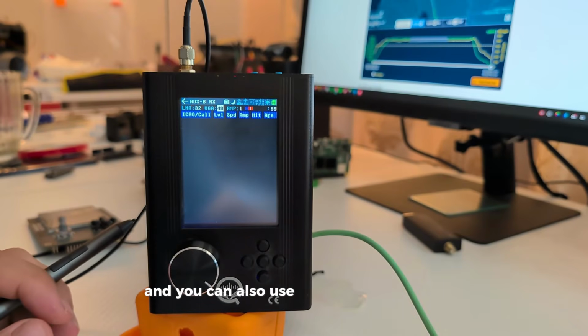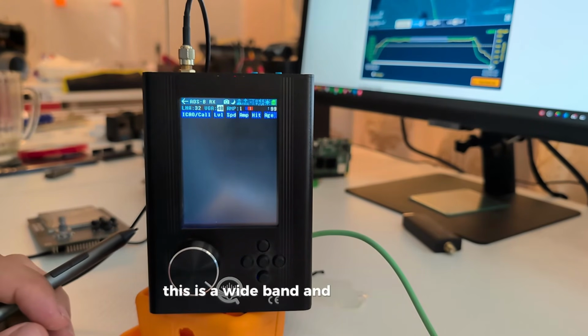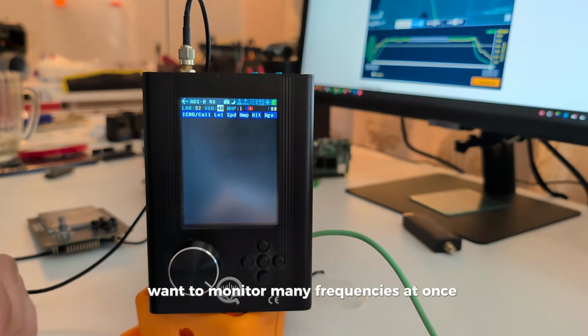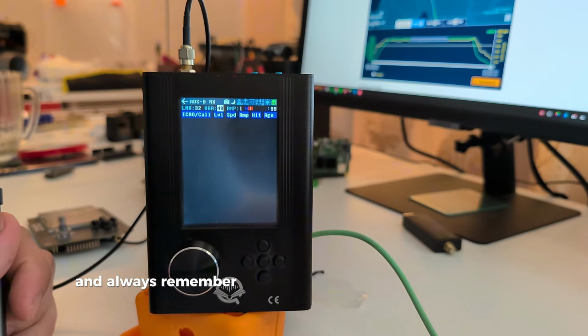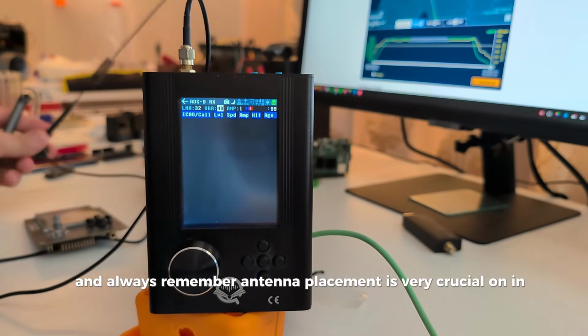And you can also use a cone antenna, which is wide band and good if you want to monitor many frequencies at once, though less optimized than the first two. And always remember, antenna placement is very crucial.